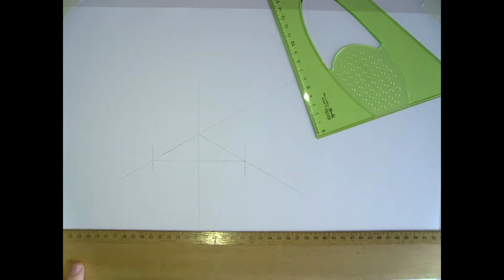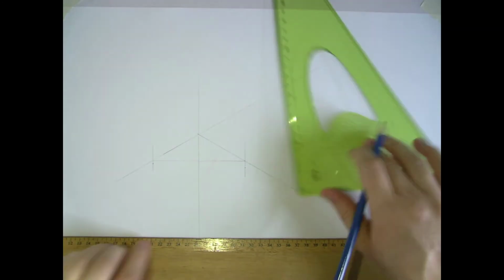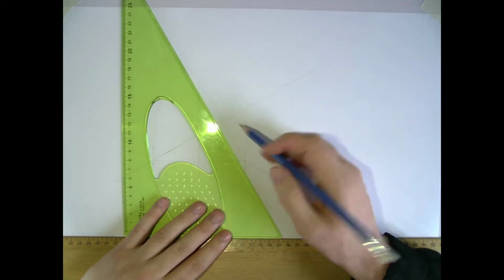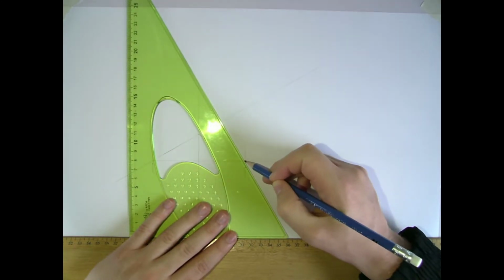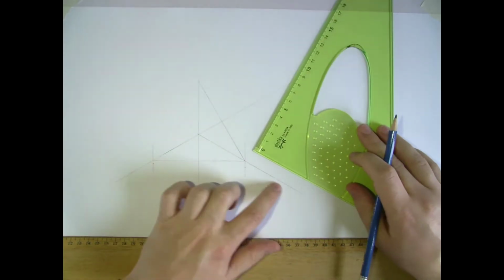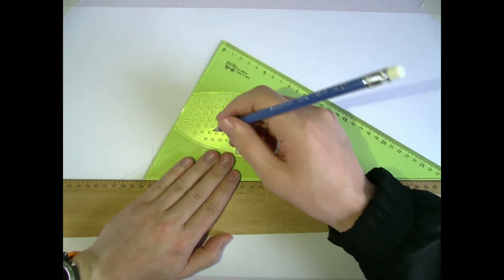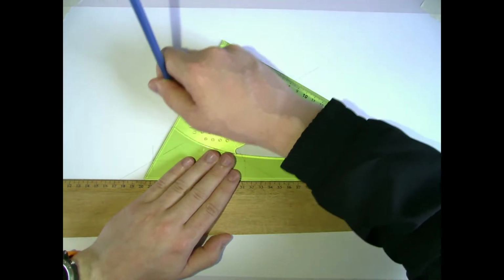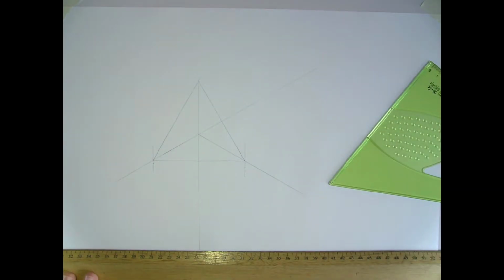Here, what we need to do next is find the lines going up along this way. So they are drawn so that they are perpendicular to this line. So this line is at 30 degrees, so the line coming out of that will be at 60. This line here is also at 30 degrees going in the opposite direction. So again, a line perpendicular to that would be at 60 degrees. So that completes the equilateral triangle and the axis AB and the X, Y, Z axis.